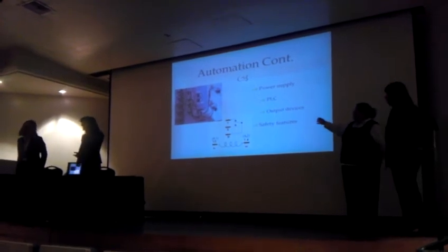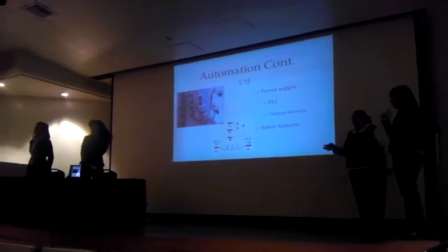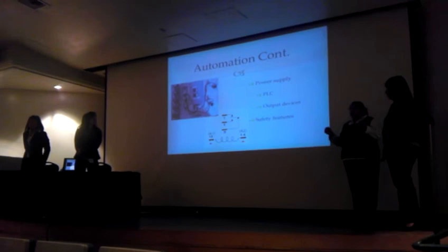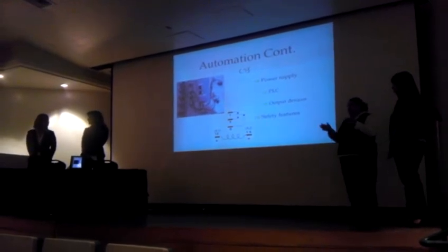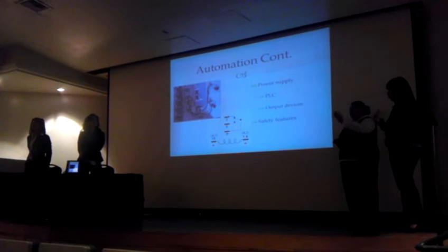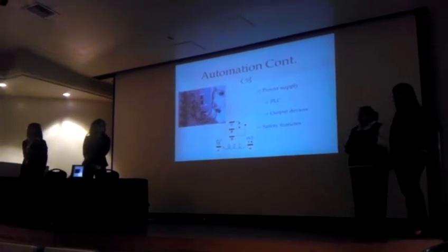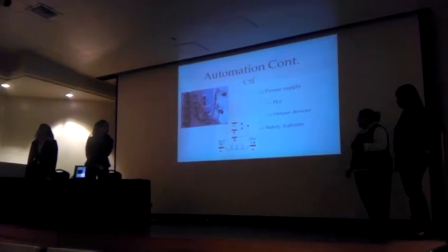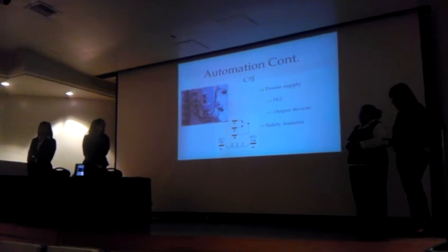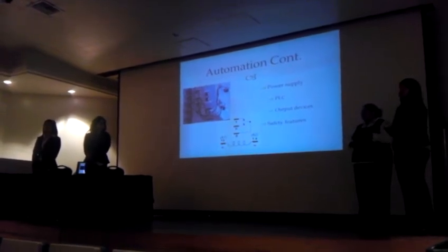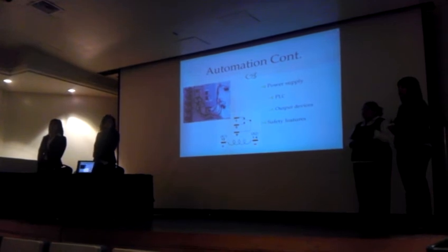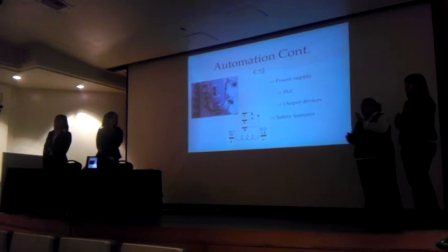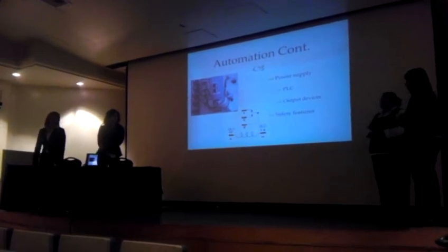The programming that was done for the PLC was done using ladder logic. Actually, when you open the program, it looks like a ladder. It has rungs. The language is read when the PLC reads the code, from left to right. Everything on the left-hand side is your inputs, and on the right-hand side is your outputs. It's actually a very interesting program. It has a lot of coils and internal coils, and it uses internal coils from the PLC itself and the internal memory of the PLC. And that's how we designed our coding to run these pumps and valves.